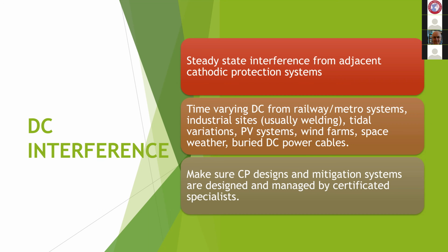But if you have a big voltage difference between 2 points on the ground, the electric current will go from the higher point down to the lower point. So it's a bit like the football moving down the gradient. And you might say, well, what's all this got to do with anything? Well, if you're building a new pipeline and you've followed all those rules about the coating and so on, you'll have a pipeline that requires very little cathodic protection current to protect it because there'll be very few defects and no connections directly to earth.